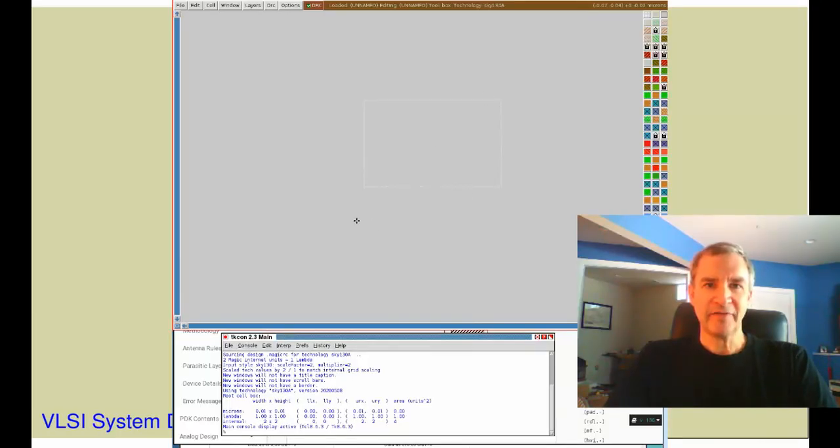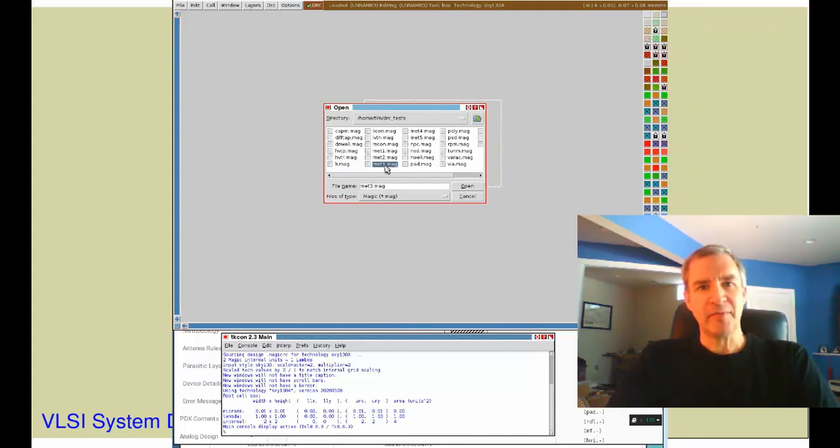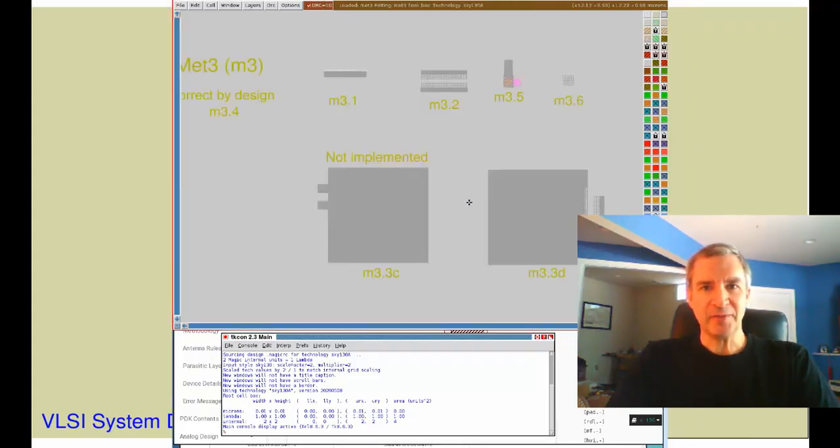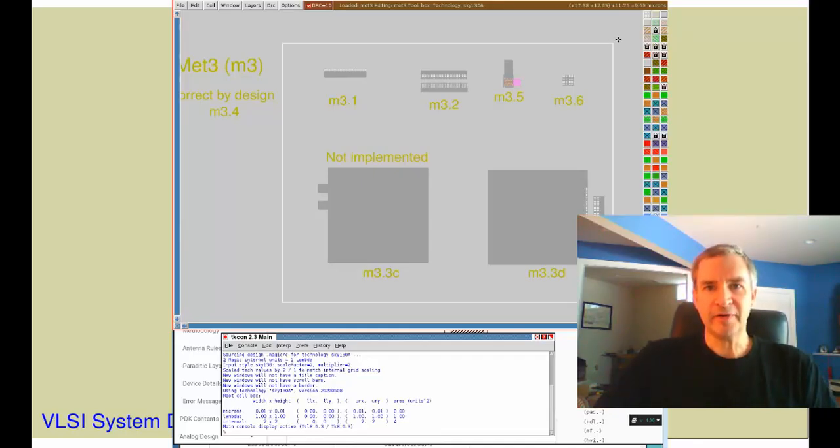Let's look at an example of a fairly simple set of rules, starting with Metal3. The name of the file is met3.mag, so run magic -d XR met3, for example. You can also just run magic from the command line and use the menu option File followed by Open to load the file. This is what you should see in the layout view. In this view, you can see that there are a number of independent example layout geometries, and most of them show some kind of DRC error, which is displayed by the interactive DRC engine as a white patch where the error has been flagged.